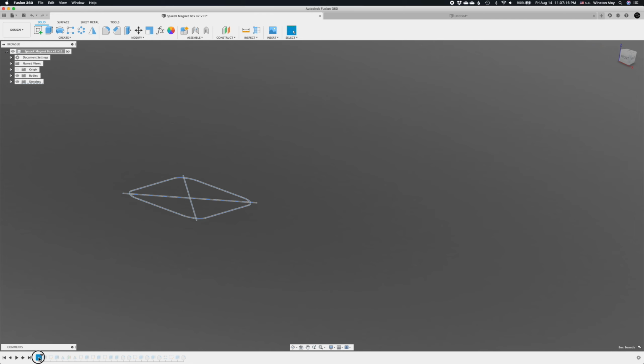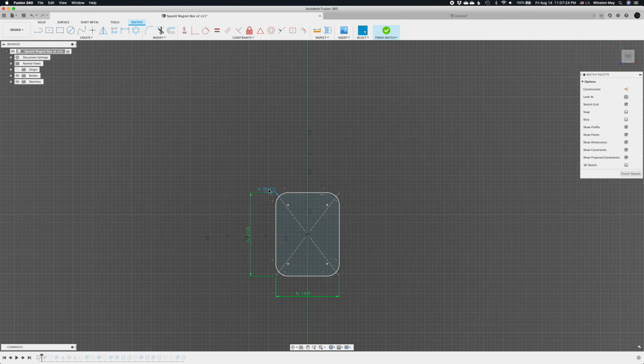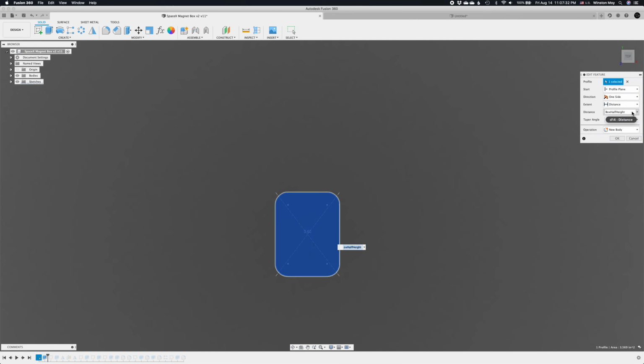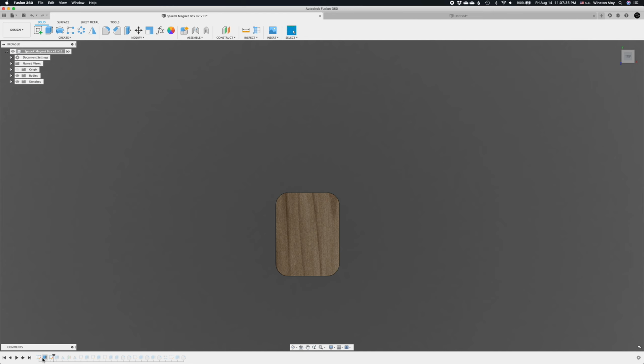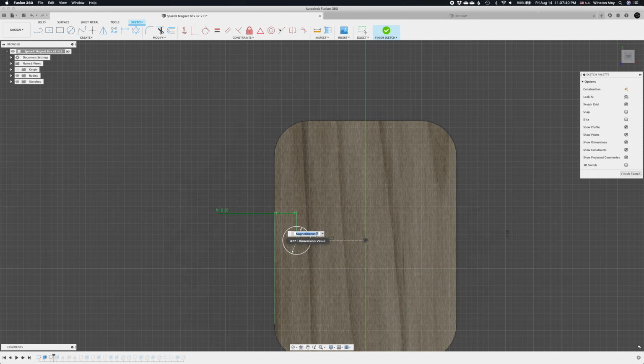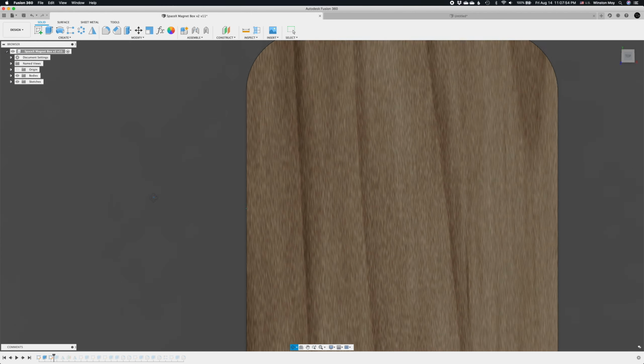First thing I did, create a sketch, overall length and overall width. And then here, this radius is also predefined, called outer radius. I will extrude that out to a height of box half height. And then the second sketch is the location of the magnet. The magnet diameter is a parameter. How inset that magnet pocket is could also be a parameter. Visually, I think using a ratio is perfectly adequate, and it saves you from having to make another parameter. It just keeps everything a little cleaner.